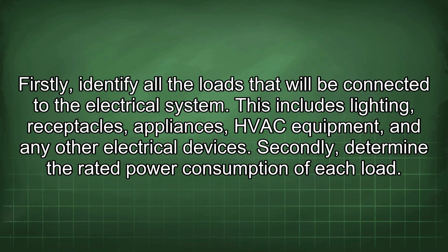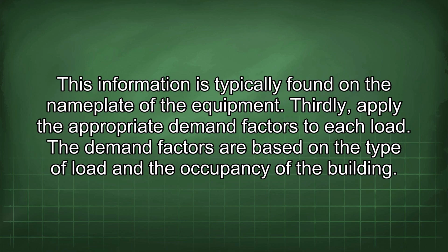Firstly, identify all the loads that will be connected to the electrical system. This includes lighting, receptacles, appliances, HVAC equipment, and any other electrical devices. Secondly, determine the rated power consumption of each load. This information is typically found in the nameplate of the equipment.